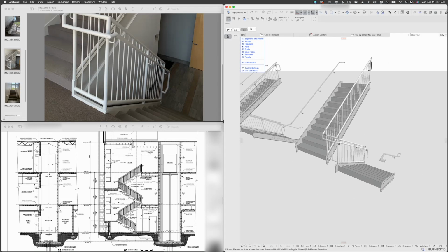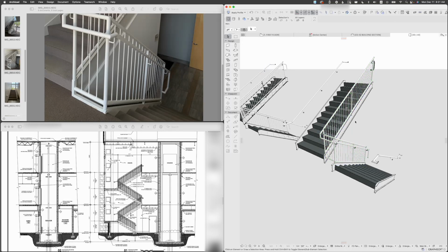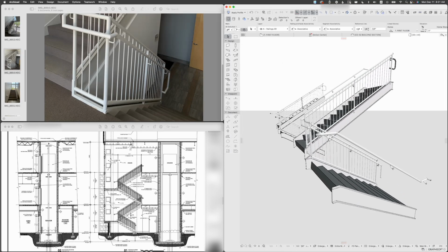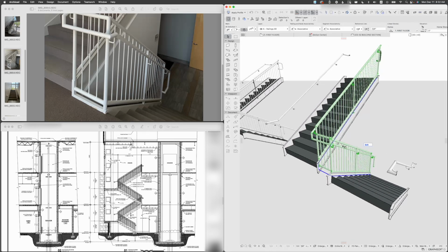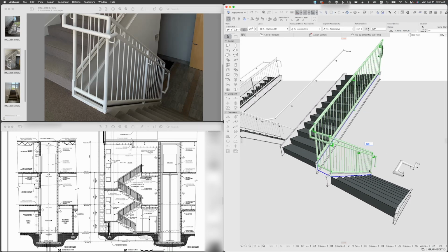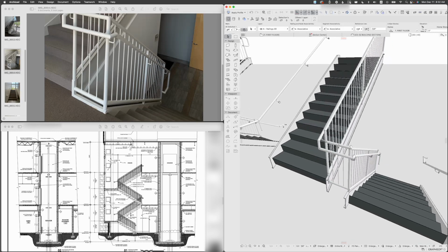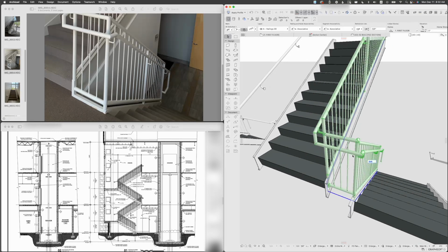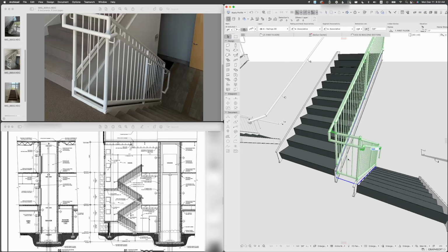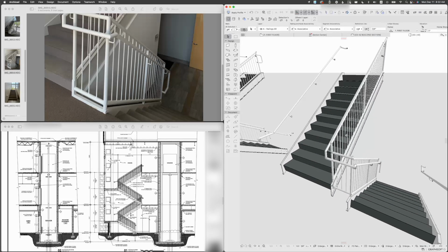Now let's escape from here, and we just realized that this method was really much easier to build the entire railing as one element that consists of 3 segments, instead of trying to build 2 separate elements and trying to connect them in the middle. We always need to avoid building individual elements if we can snap to the existing conditions and just continue the segments and have one element. So, okay, this is looking good.